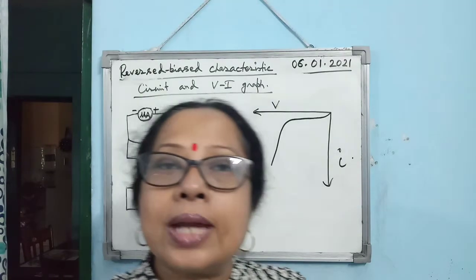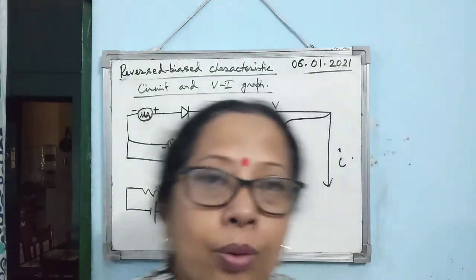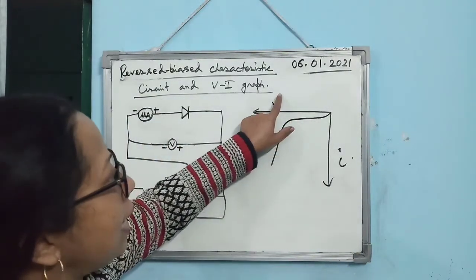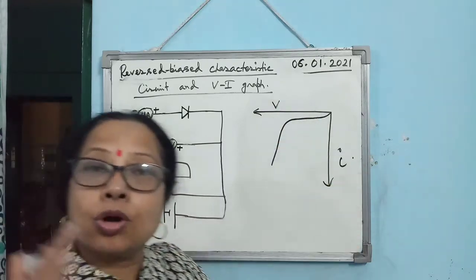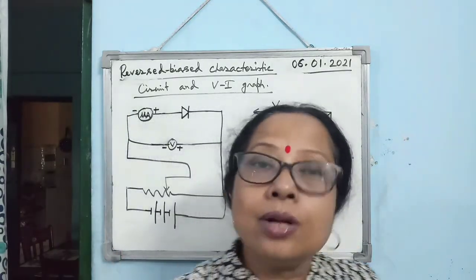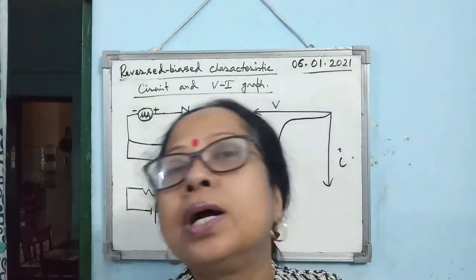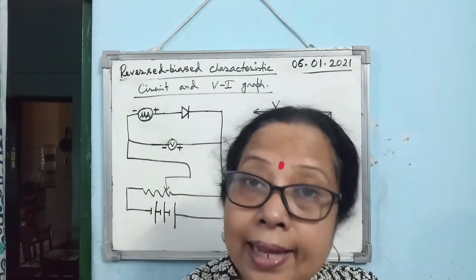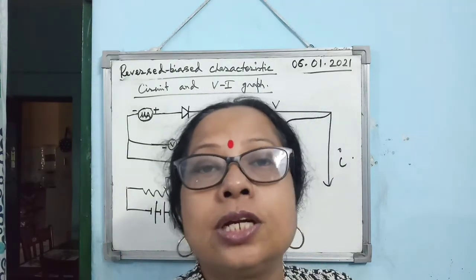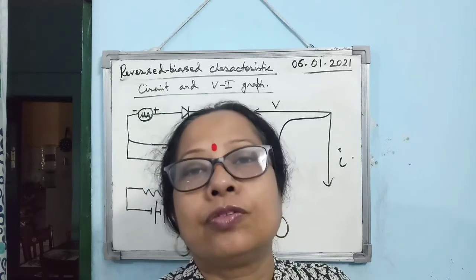So this is known as Zener breakdown or avalanche. Okay, this is known as Zener breakdown. Means when the applied reverse biasing voltage crosses certain limit, then what happens? A large number of covalent bond break across the junction of the diode.